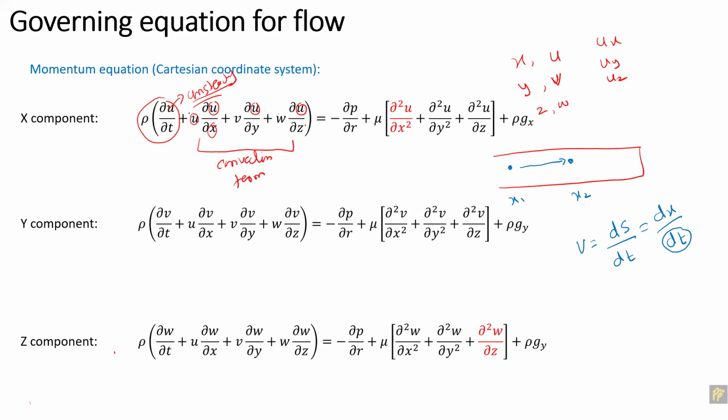Similarly, we can see that everything is multiplied with the velocity. So this velocity actually is coming from outside. So it will move by this velocity. So the mechanism here is not time but the velocity. Definitely the velocity will contain the time, but right now this is a steady state case. This is like a positional vector. It's not changing because of time, but it's changing because of the position vector, because of the velocity. This term is known as a convection term. Like we are putting some velocity, this is convecting from one location to a second location. So this is different from the transient term.